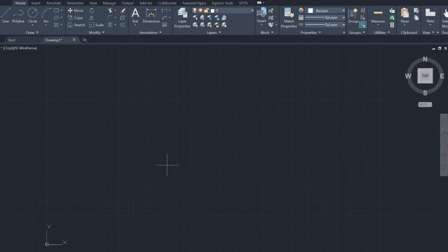And then enter. Sir, you don't even need to hover your cursor over the command line. You can just type immediately, even without clicking on the command line. Look at what I'm doing. I just typed L, and then enter. And then, you are asked the same question.